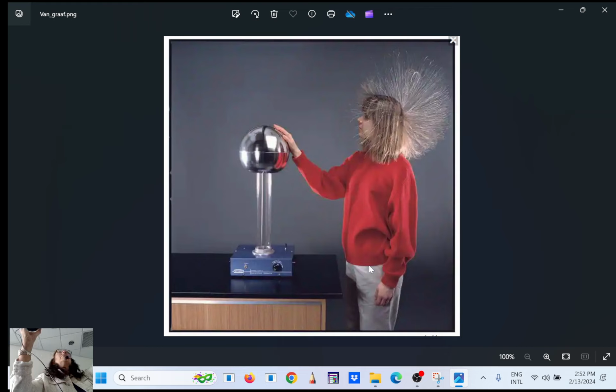If you apply a voltage across that tube, you will force the electrons to move inside, right? These electrons will kick mercury atoms, and the excited mercury will emit light that will be absorbed by the phosphor around here. But you need to apply your voltage, right?